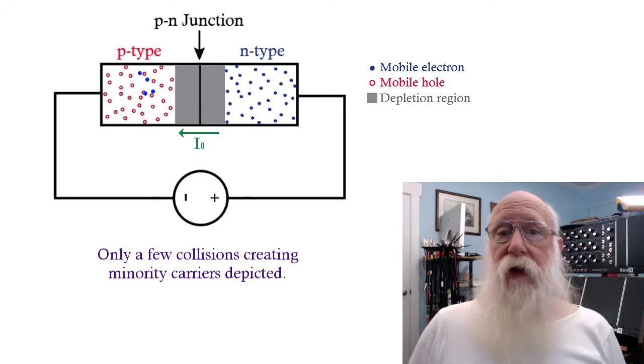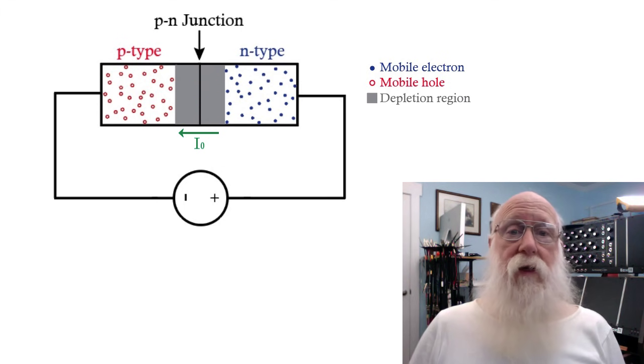The current can get very large very rapidly, and unless you do something to limit the current, the junction can get so hot that you destroy the device. So in general, if you're trying to run a device in avalanche breakdown mode, then you would put in some sort of additional component or components to limit the current. We'll see that in a moment.